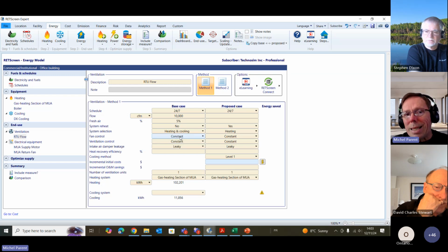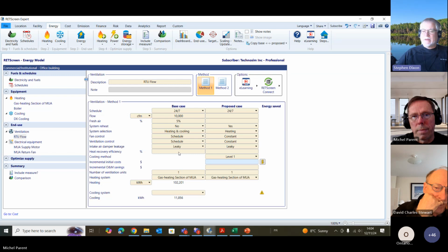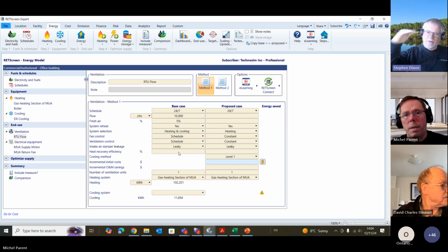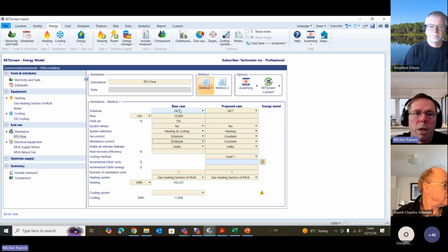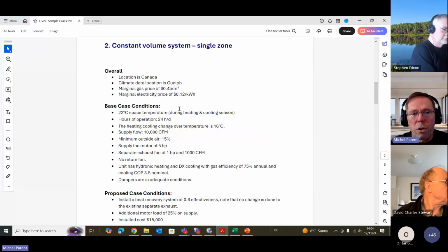Now, it's 24/7, I'd say by habit. And Stephen, you may do differently. Yeah, I always put, good practice, use schedule, because later on, and we're not going to use it in this example, we may change a schedule, in which case we don't have to come back here and change it from constant to schedule. So I always set this to schedule so it follows whatever's at the top of this column. Exactly. And obviously, because it's 24/7, the fact that we go from constant to schedule is not going to change anything, but it will be very useful later on.